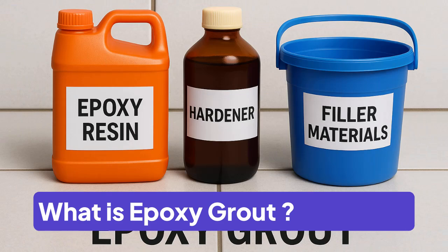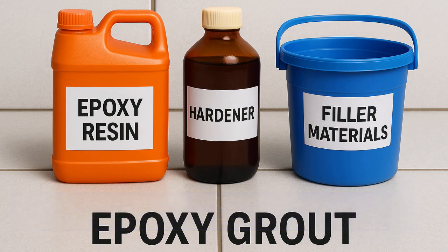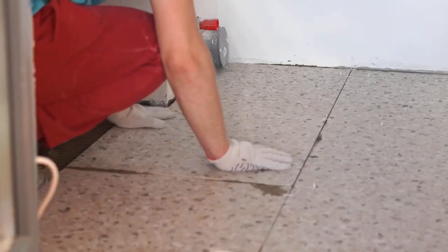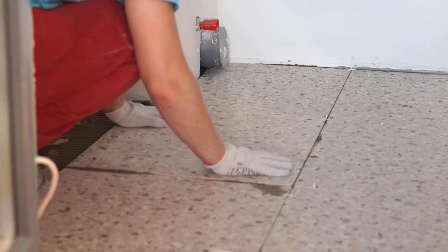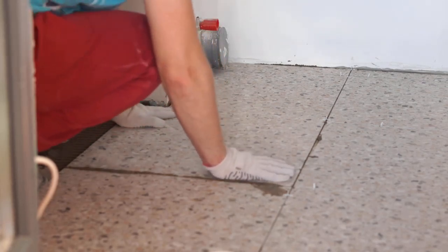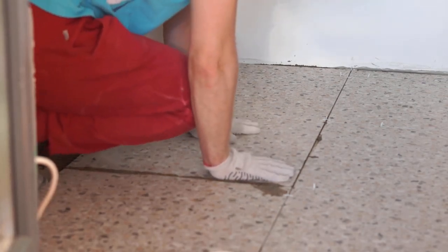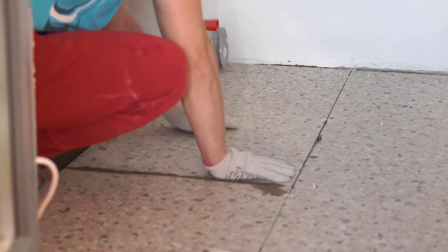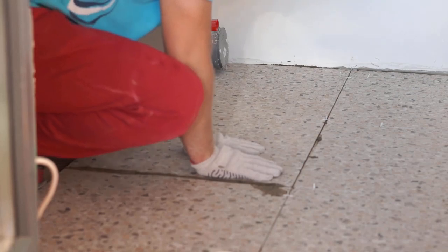Now what is this? It's like using steel instead of bamboo. If you compare cementitious grout to bamboo, then epoxy grout is like steel. That is how big a jump it is in performance. So performance-wise, it's the ultimate one. So where can we use this epoxy grout? In commercial kitchens, hospitals and laboratories, heavy-duty floors, under machinery and for anchor bolts.